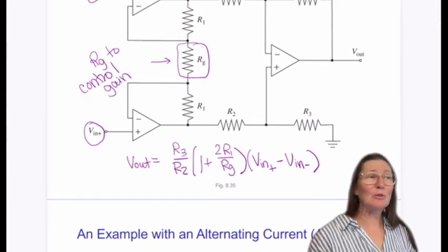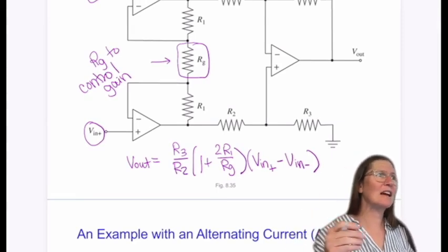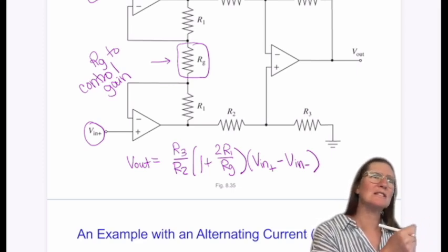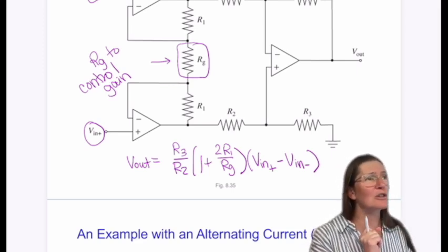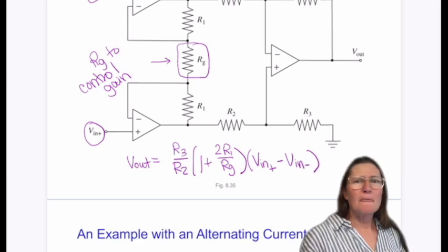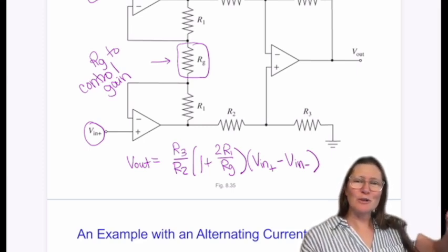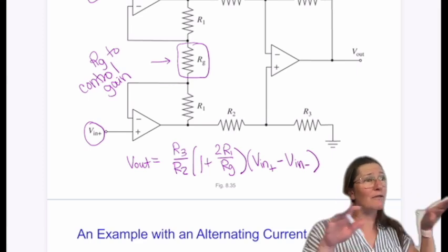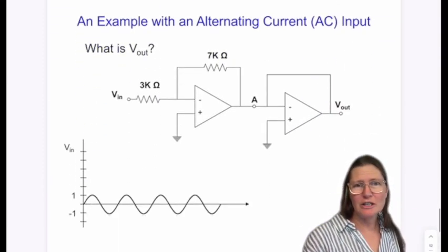Okay, so it's nice that there's already a chip that has multiple op amps on it like this, and it's designed so that I only need to tweak one resistance to change this gain instead of having the two. And usually it's an external resistor, like a potentiometer, that you change until you get a zero value of where you want to start. And then you can change it.